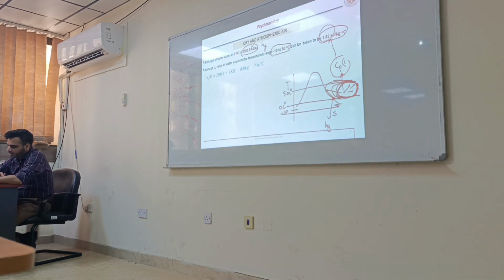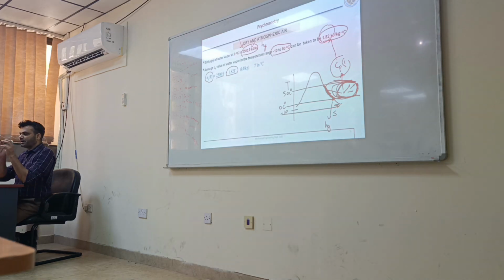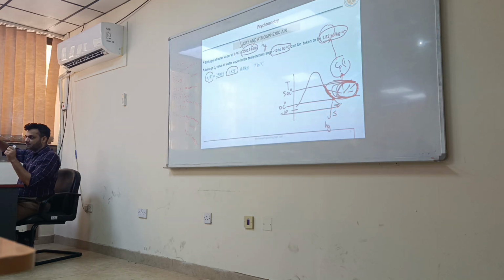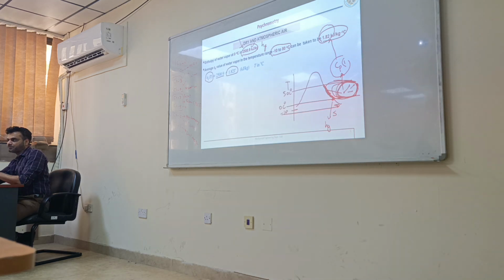So I can find out water vapor enthalpy as Hg plus Cp t. Hg till this point. Now here Hg is shown only for 0, but between 0 and 50, all these Hg values are very near to each other. But now if you go further, you have to add Hg plus Cp t. This is saturated, but from saturated to superheated, you have to add Cp t.